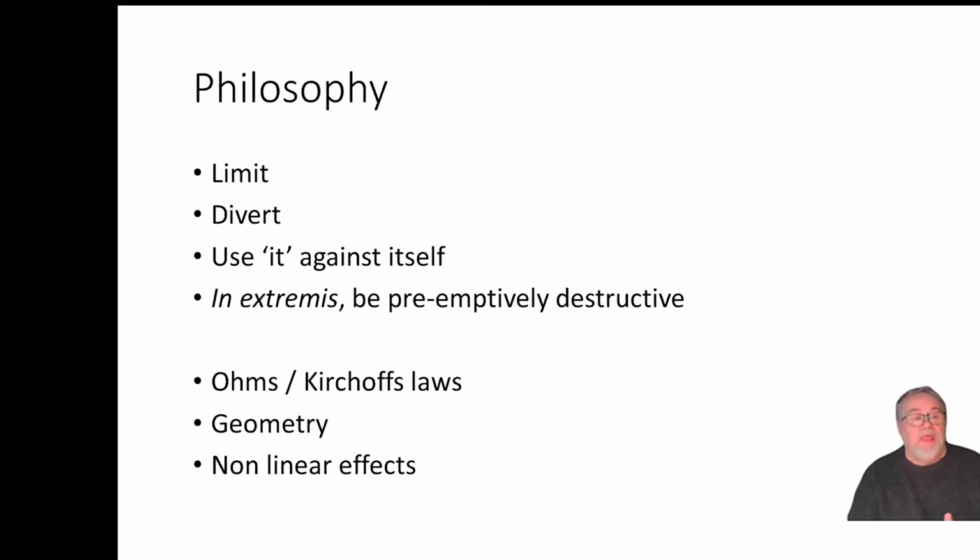The philosophy of protection is, first of all, if you can limit the thing that you're trying to protect from, if it's voltage or current or heat, limiting it is good. If you can't limit it, then divert it, make it be somewhere else where it's not going to do any harm. We always use the phenomenon that we are protecting against itself. Every one of the phenomena has side effects. Voltages cause electric fields, voltages cause currents to flow, currents cause heat, heat causes melting. There's always a side effect that you can use to detect the phenomenon and use it to implement protection.